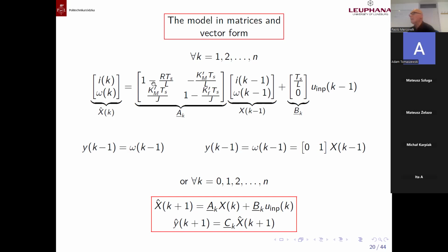We basically collapse into the identity matrix, and we will see later that in the presence of the identity matrix, the system is not controllable. This means it's not controllable, but it is also not observable. I mean, it's not controllable if I have just one input, but the controllability we basically lose from here. But also the observability, I will tell you about the observability later, a little bit intuitively. We can demonstrate that the system is not connected, and then measuring a part of the state, I cannot observe the rest of the state.